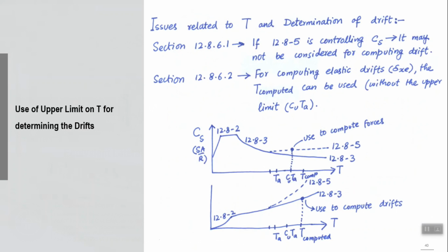In this regard, I forgot to tell you, actually it was my mistake, that I was saying that you may use a different model to calculate a different time period. I missed that option: as mentioned by someone from you, why not make a different load case within the same model, and the software allows you to give your own time period also to be used in the ELF procedure, right.